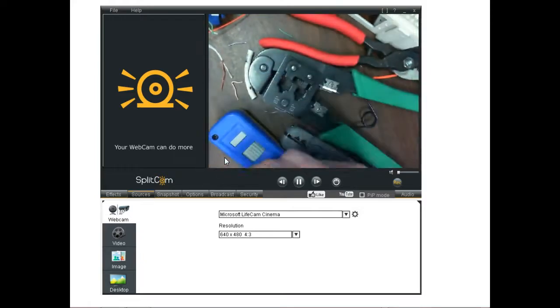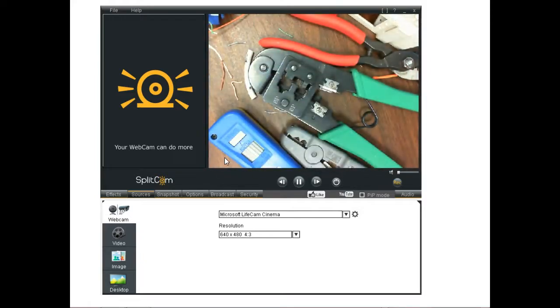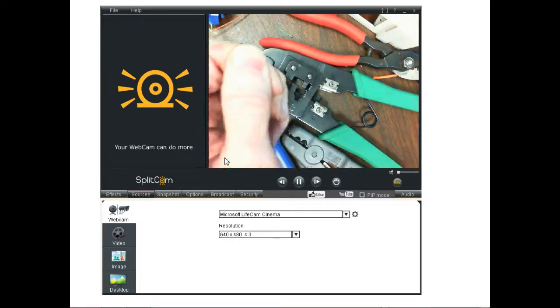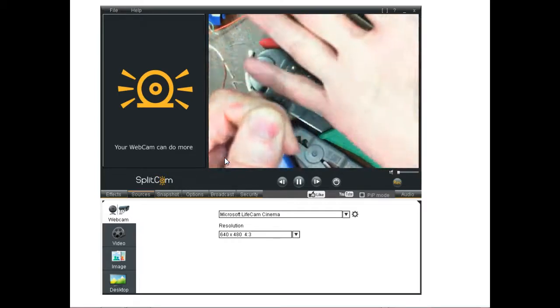And so that's why when I strip it off probably 3 inches. That gives me the ability to do what? Get all the twists out of there. It also gives me the ability to have them nice long wires out there so I can arrange it into the right color, right? Y'all understand that? And once I get it into the right color, I clamp down on it with what? With my thumb, and I never take it off.